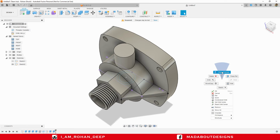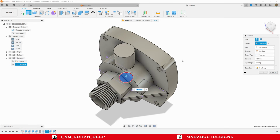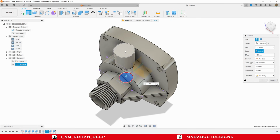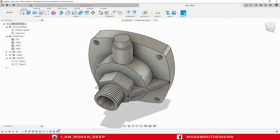Right click and repeat extrude. This time click and hold. Select the inner profile. Change the start plane to object and select this surface as the object. So our profile will be extruded from this surface instead of the profile plane. Here it is. Give it an extruded distance of 5 mm and operation join, click OK. Hide sketch 2.